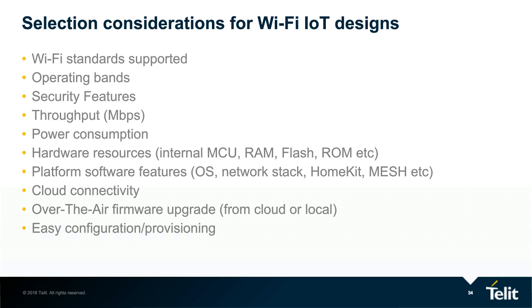So to make Wi-Fi viable for battery-operated low-power devices, various power-saving schemes have been implemented in both SoC and software, apart from the standard IEEE protocol, which is governed by the 802.11 protocol. Now, these system power-saving schemes are vendor-specific, but made sure to be interoperable with other devices in the network.